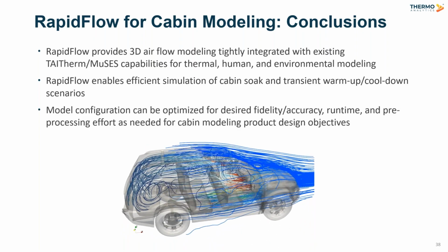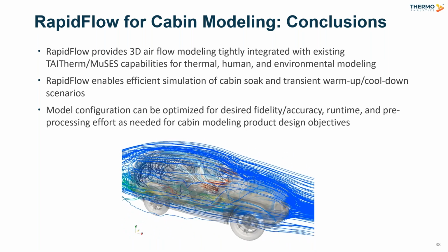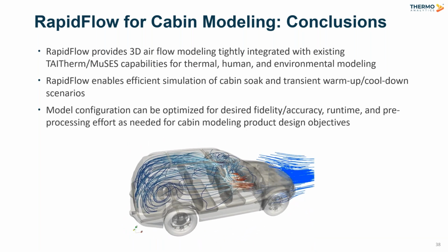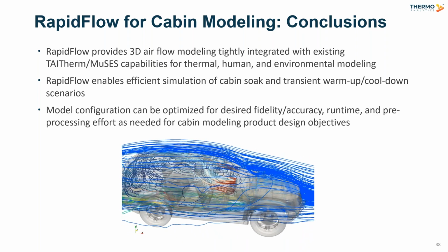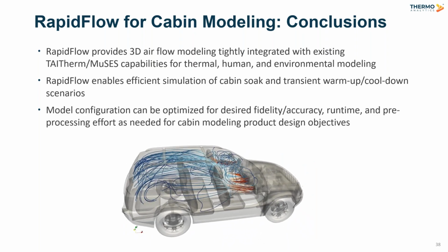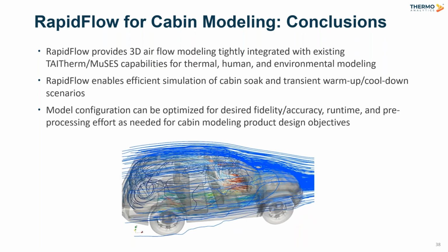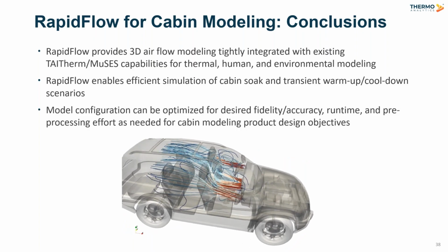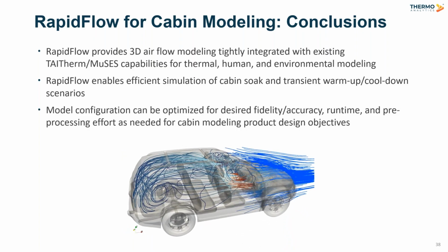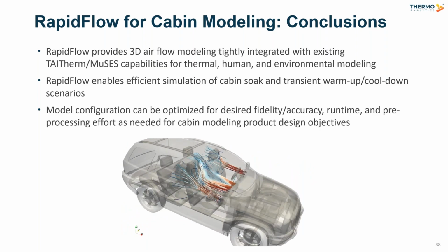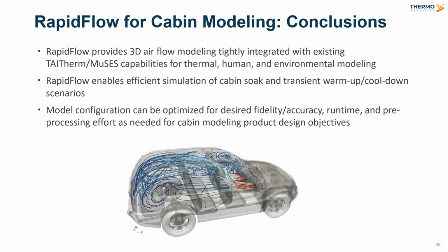It is important to note that just in the same way that heat transfer coefficients from CFD models with different resolutions don't necessarily compare numerically, the same is true with RapidFlow. So it's often important to not just directly compare the values of heat transfer coefficients, but look at the bigger picture of the convective heat flux and the nearby fluid and surface temperatures.